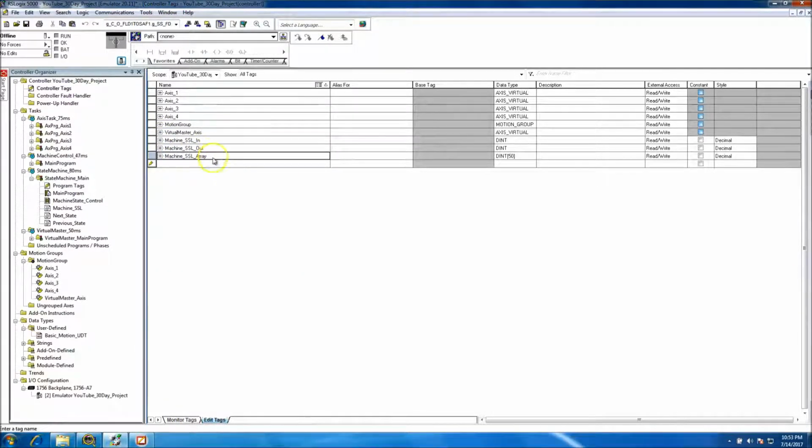So now that we have those in place, we want to go ahead and put the HMI status, like where the machine is that we're going to be using. We're going to be doing a graphical layout, like a state indicator, a multi-state indicator, to let you know where the machine's at that point in time. So we'll go ahead and throw that in there. So machine state, and then we'll call that the number. And then basically we'll keep that as a DINT as well.